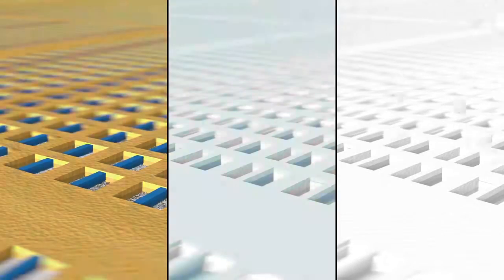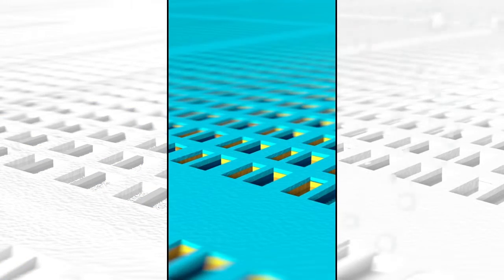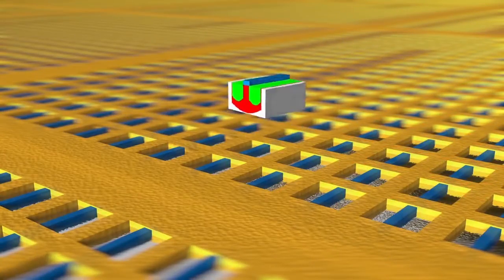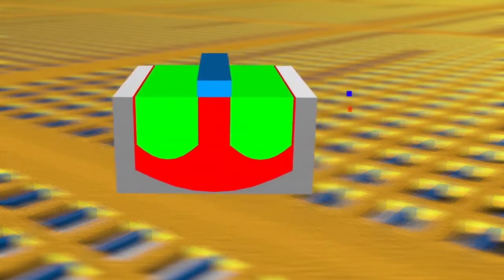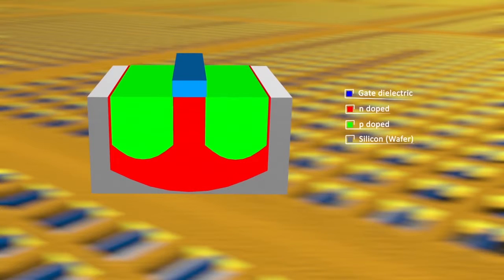Finally, the gate dielectric is created, in which photoresist will be used to make source and drain areas through the implantation of foreign atoms. This is the fundamental structure of transistors. At this point, the front end of line is completed. From here, the back end of line begins.